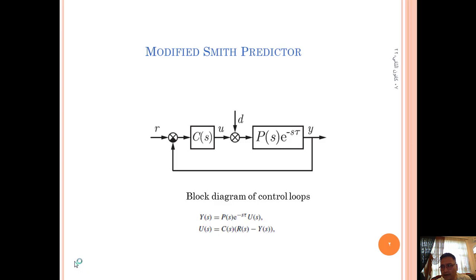An accurate prediction is able to completely eliminate the delay from the feedback loop. This means that the Smith predictor is able to remove the effect of the time delay on the poles of the closed loop control and achieves the delayed response of the delay-free plant P(s) subjected to controller C(s).